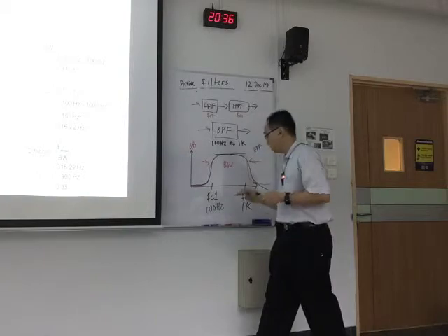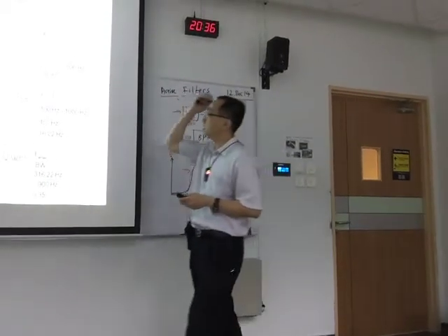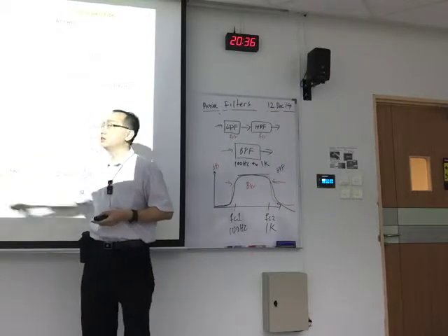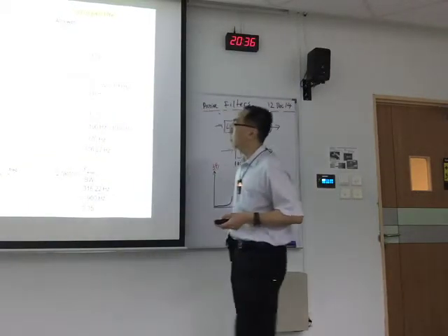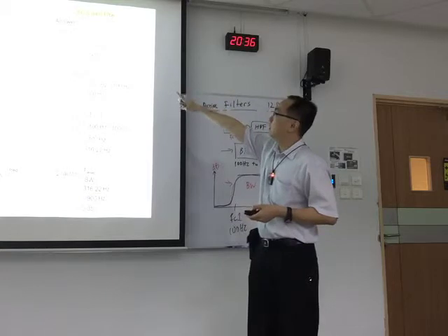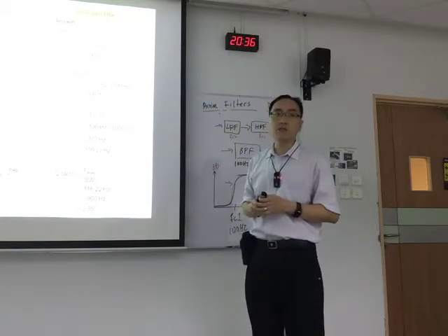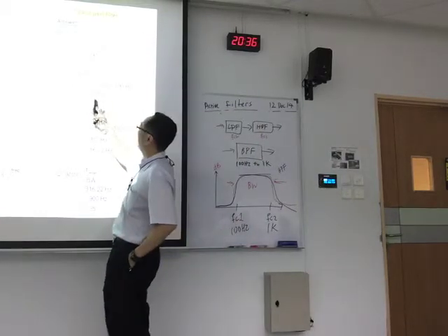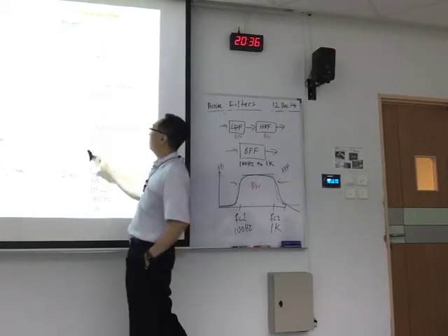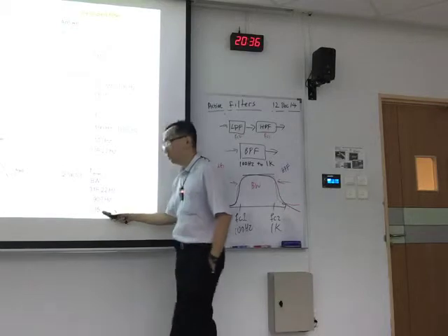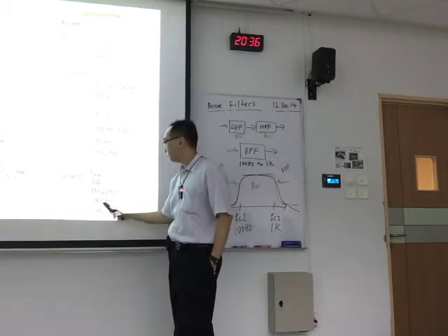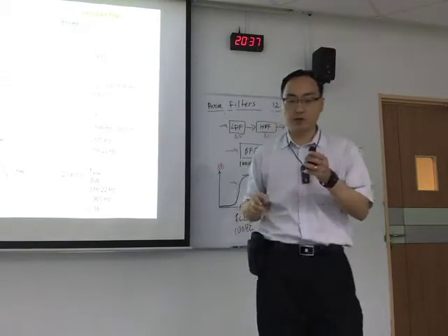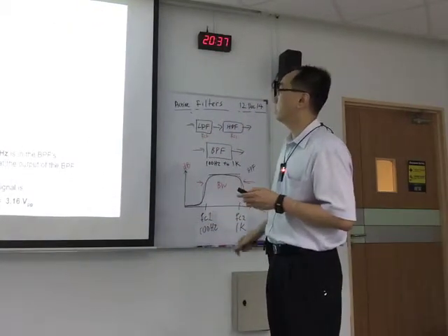Okay. So you are supposed to calculate all those things that are given. Sketch the response. Okay, no problem. You can sketch this one. Then what else? Calculate the Q factor. So you can calculate the cutoff frequency FC2 minus FC1, right? You get the bandwidth. So it's 900 Hz. Then you can calculate what is the Q. Okay, so this is a worked example.